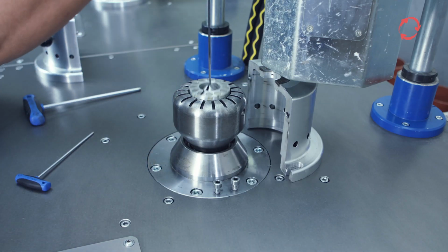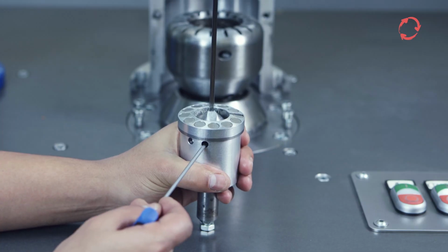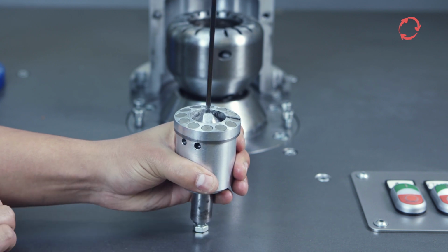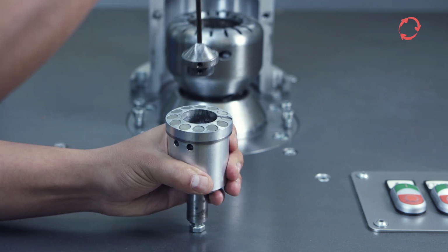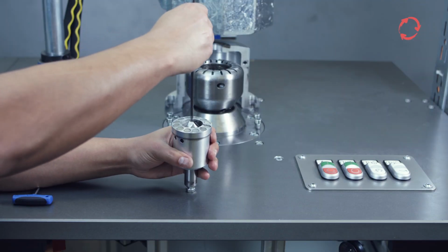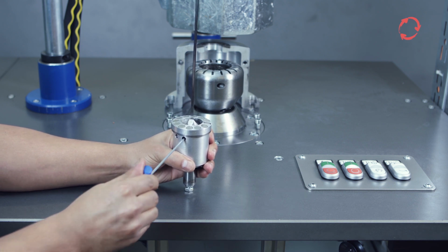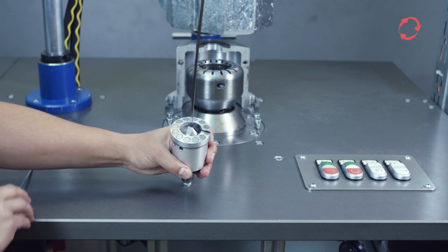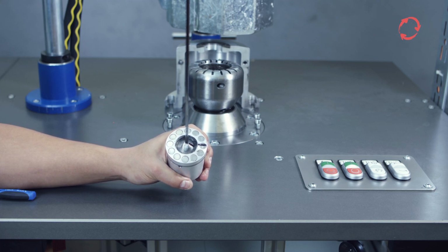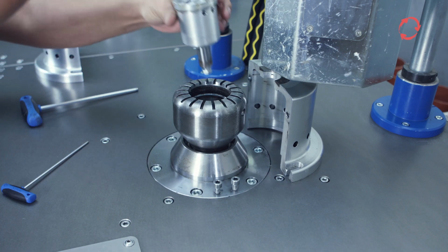After the previous step, you can pull up the intake. After loosening the clamping screws with the 3mm Allen key, the mandrel can be removed from the intake. To insert the new mandrel, follow the reverse order of this process. When doing so, screw both the clamping screws back in and pay attention that the mandrel is positioned perfectly in the intake. When inserting into the intake, the narrow side of the mandrel must again face the marking.